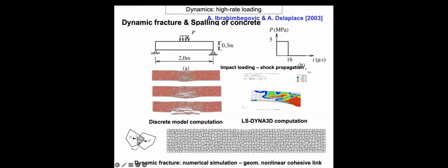Basically, if you have a 3-point bending test, but in dynamics, that starts by hitting it from a certain height h, then the velocity when you hit the beam is the square root of 2 times g times this height h. And so this starts propagating downwards, comes to the free surface, reflects, becomes a tensile wave, and the materials which are sensitive to tensile stresses will basically break, and then you can have this part of the structure with something like a scabbing phenomenon, spalling of concrete.